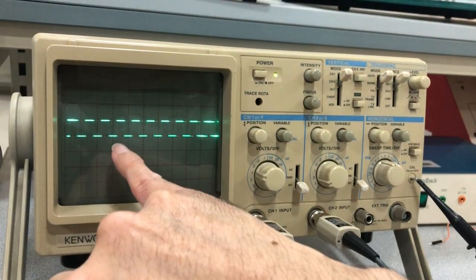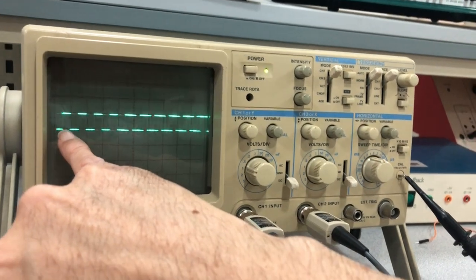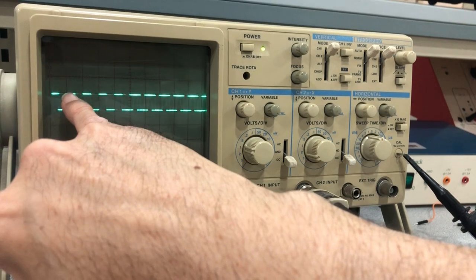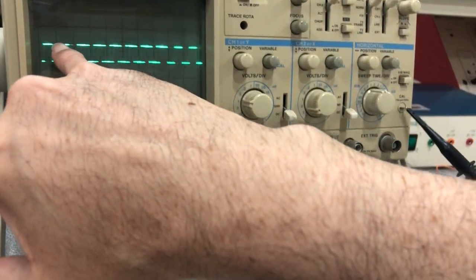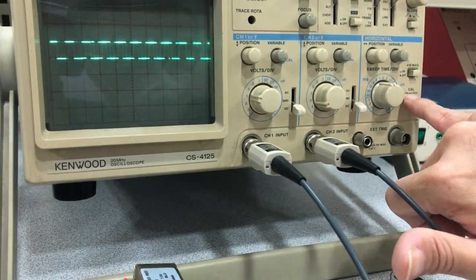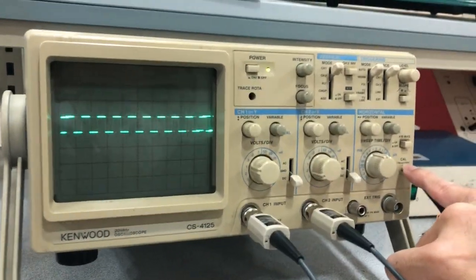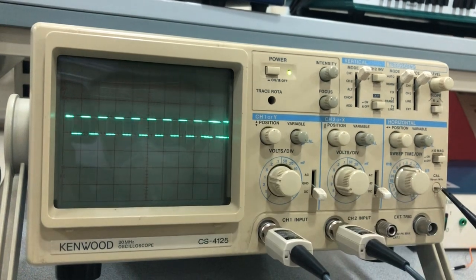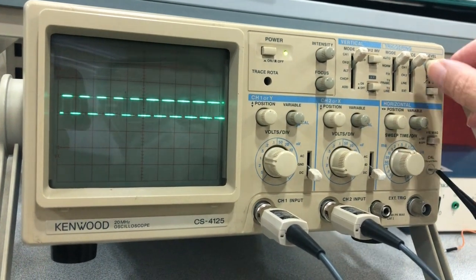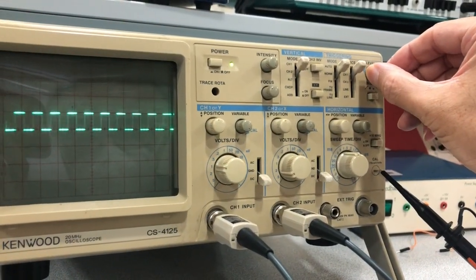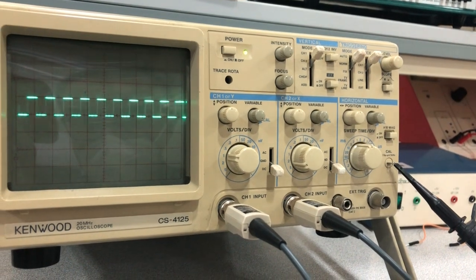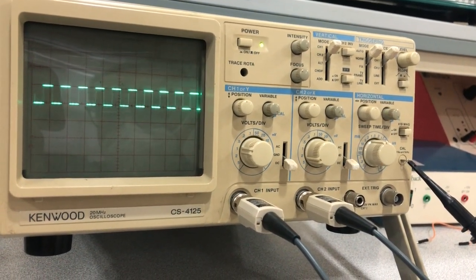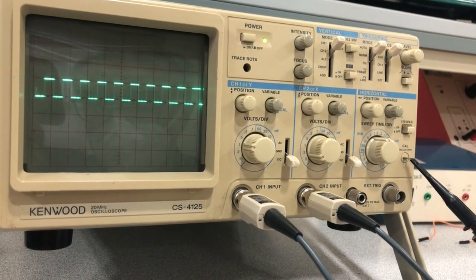This horizontal line cannot go below this time axis and cannot be above the highest peak of the signal, which is 1 volt peak right now, as indicated here. It's 1 volt peak to peak. So the imaginary line has to be between 0 and 1 volt in order to cross my signal. So I'm going to play with it. Okay, as soon as it became between the minimum of the signal and the maximum of the signal, there's an intersection.